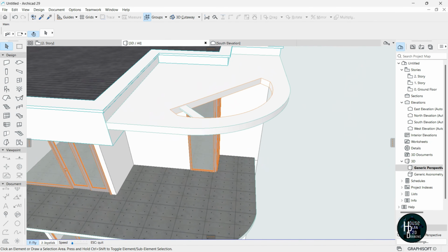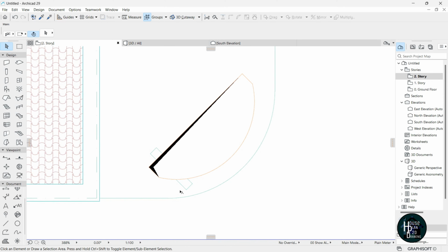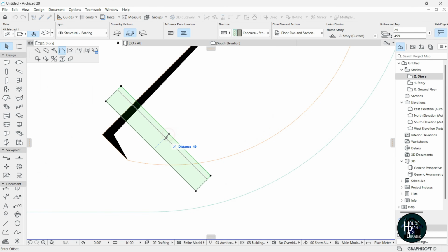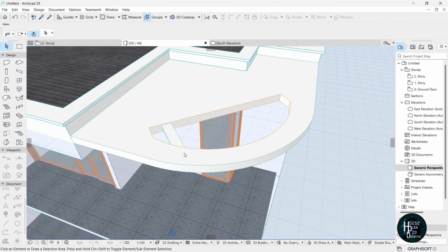So as you can see, we fixed that. So all we want to do is just make additional adjustments concerning the width. Go to the second story, so select this, click this and just reduce it like so, and let's try also reduce this also like this and reduce this to the side here. Now go to your 3D model and you should have a perfect look like this.